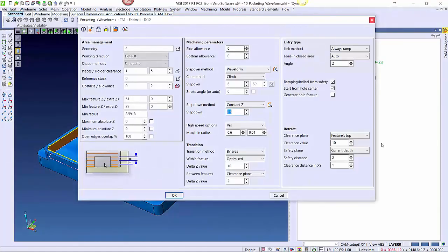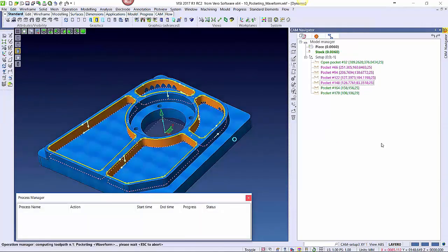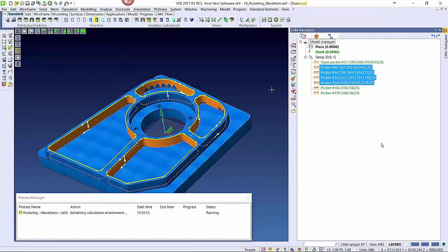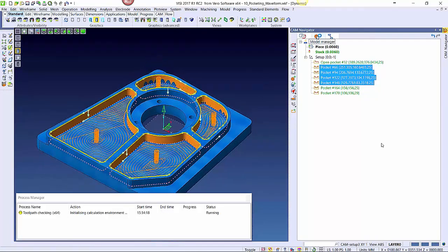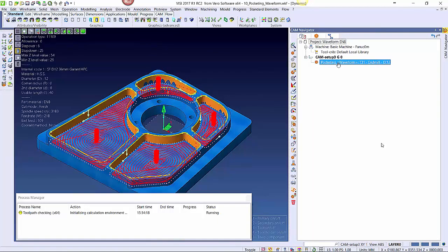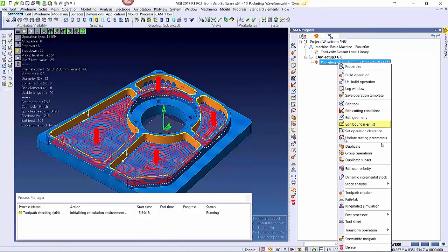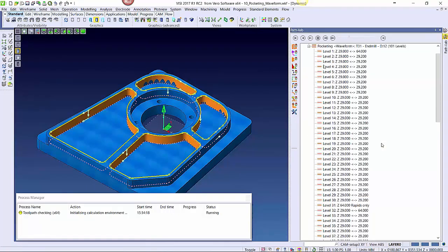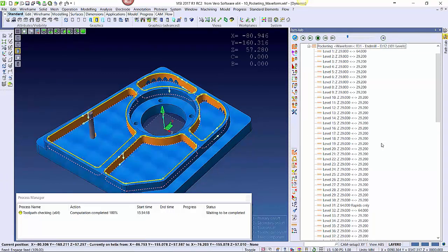It's going to really speed up these material removal rates for us. That roughing, get it all out, get it out of the way, and then come back in and maybe do that final pass on some of those things that are not as crucial, or come back with a profiling to get those tolerances right in spec what we need.